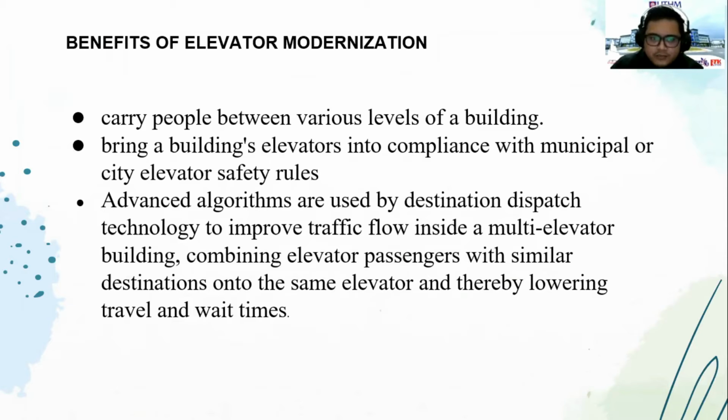Okay, next slide is our benefits of elevator modernization, which is the reason why elevator modernization is important. It's important to carry people between various levels of the building and to bring a building elevator into compliance with municipal or city elevator safety rules. And also the advanced algorithm uses destination dispatch technology to improve the traffic flow.